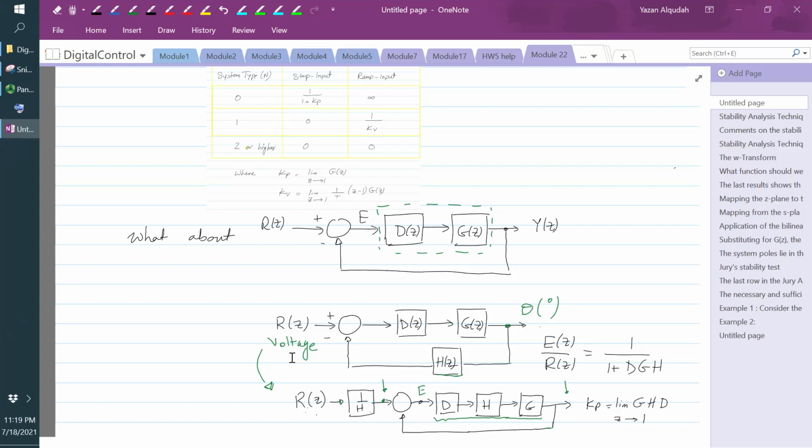Now one thing we can do, which we've done in linear control, is rearrange and get an equivalent transfer function of the one that I have here by multiplying R of z by 1 over H and removing the H of z from the feedback loop and adding H of z in the forward loop.